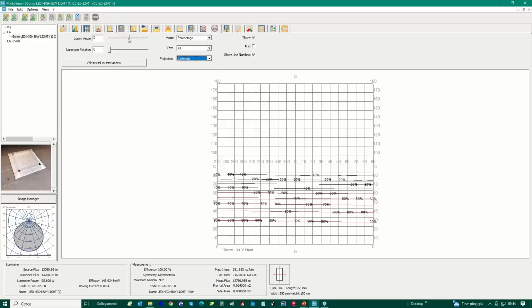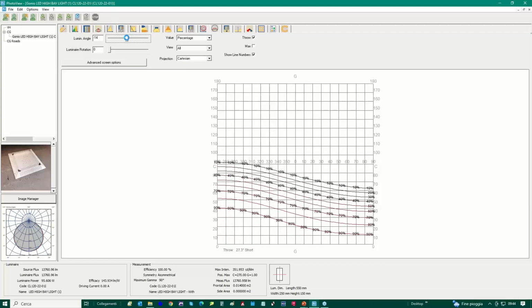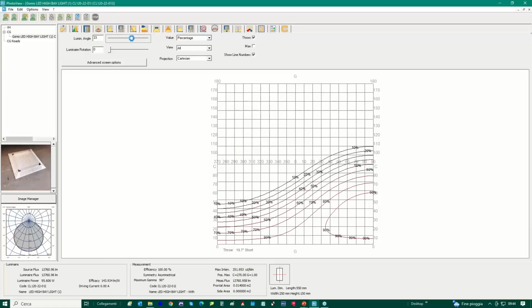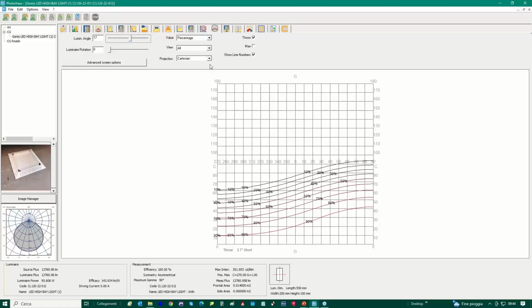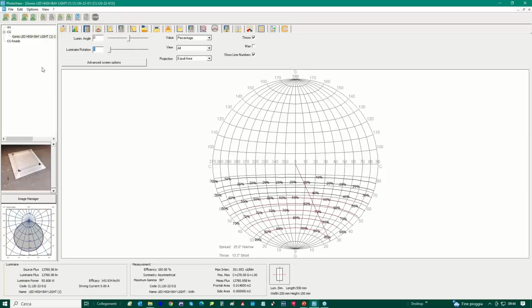So from here, it is possible to turn the luminaire. Over here, we are giving a tilting angle, so you can see that the flux is directed in a different way. So let's say that we prefer to visualize in this way. Whenever you tilt the luminaire, the flux is moving, and so it is changing the visualization of the isocandela diagram. So let's bring back to 0.